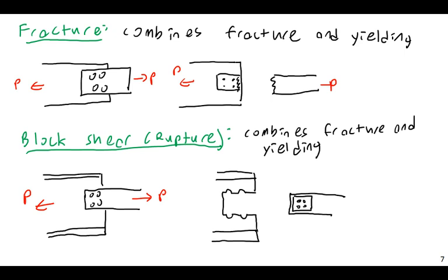So you might be joining a wide flange shape made of A992 and connecting it to another A992 shape with a splice plate made of A36. That's entirely common. So in the equations that we're going to look at, you can't just say, oh, this thing has more cross-sectional area, it must be fine. Well, the one with more cross-sectional area may be made of a weaker material. Getting all tongue-tied. So anyway, we'll look at this.